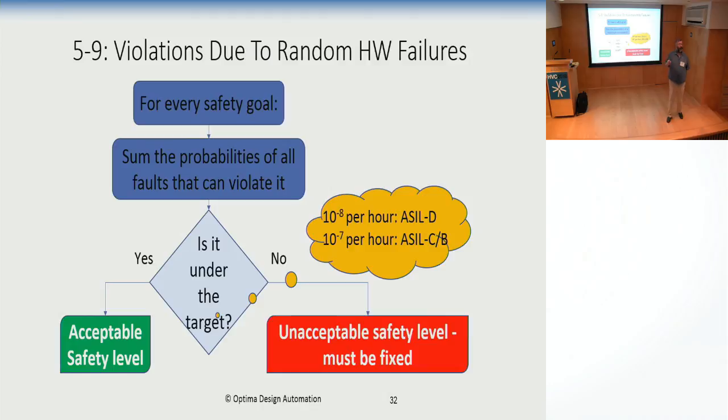For example, for soft errors, we know the radiation rate for New York City at sea level, and you can correct for other places, but the difference between sea level and 1 mile high is not that big, so you can average it out. You know the probability for a bit flipping, and then you decide how many bits are critical and multiply the probability that they will be critical by the probability that they will be hit.